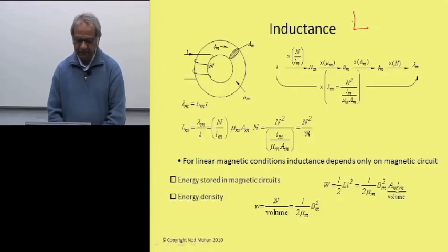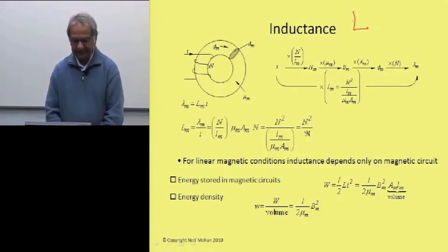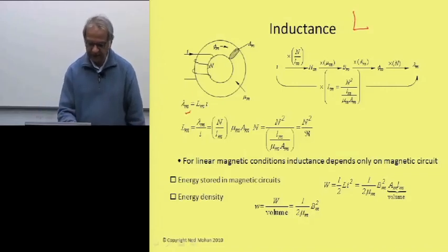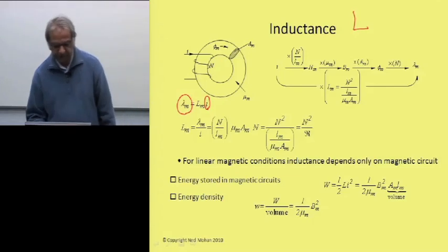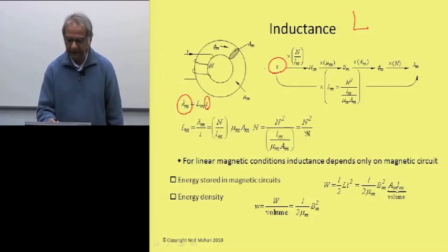Well, first of all, we should recognize that the inductance that we define is really the flux linkage of this coil divided by the current here. Okay, so let's say that we introduce some current into this coil, and this will produce a magnetic field intensity, H sub m, in this core, which is the current times this term over here.